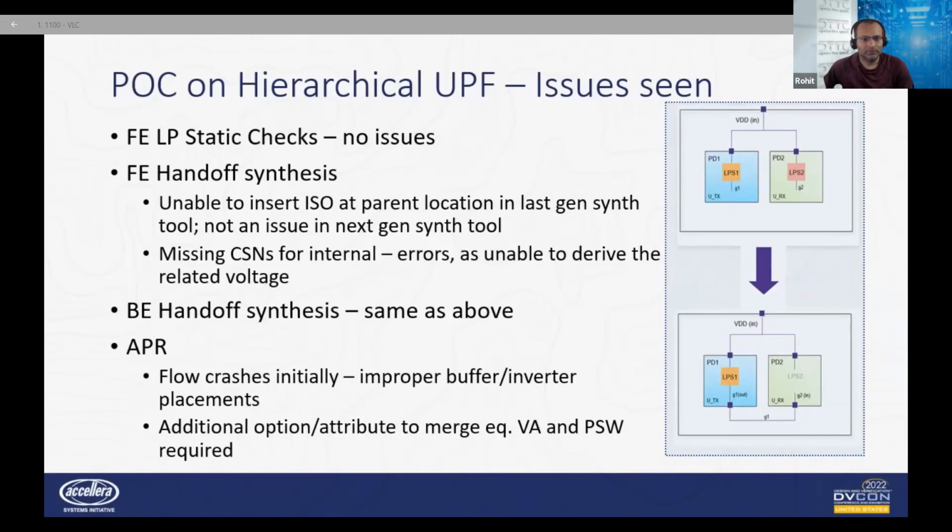During the APR flows, there were a few crashes initially because of incorrect buffer and inverter placement. Then we cleaned that up, and also to merge equivalent power domains and equivalent power switches into one power switch or one power domain or voltage area, we got the command from the vendor and applied it in the design, and then we were able to proceed.